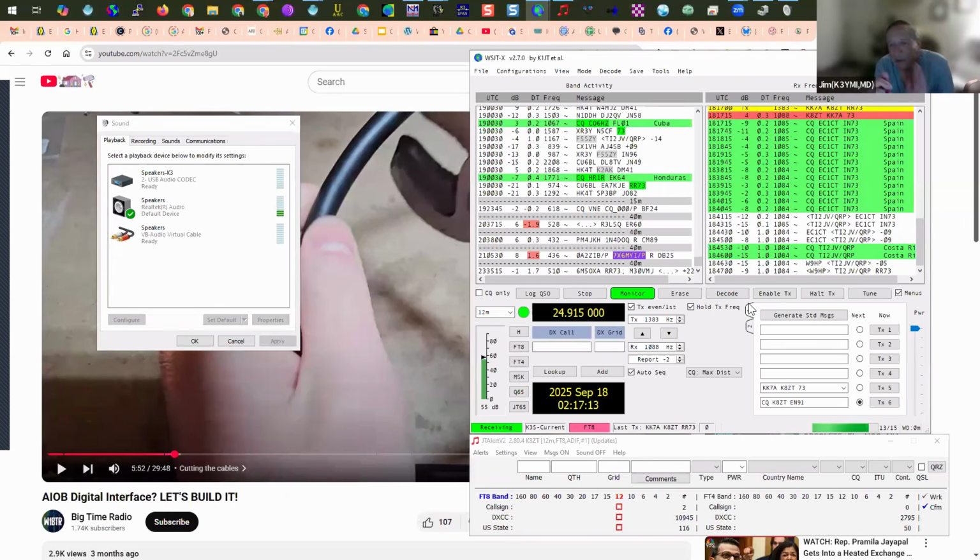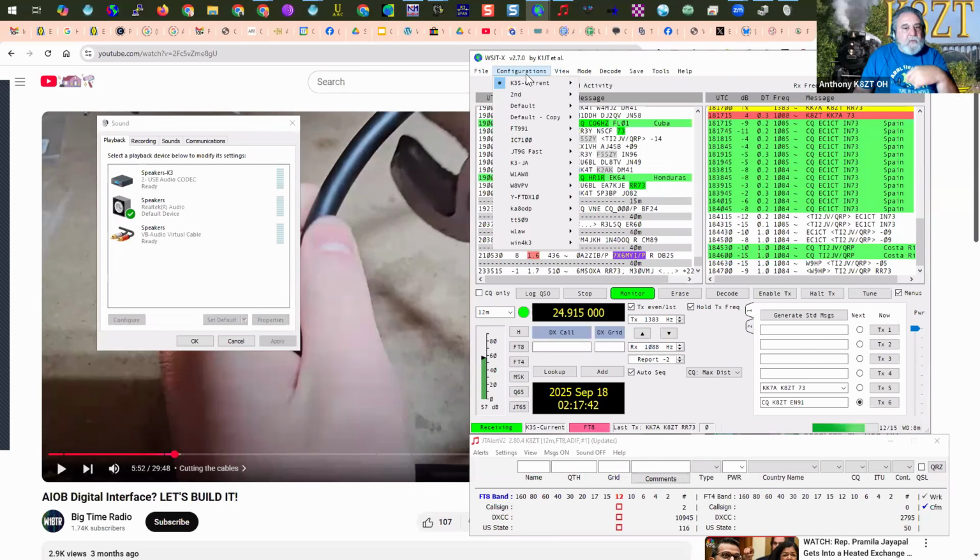Right, so let me be clear. I'm not going to run the 7300 and the Yaesu radio simultaneously. Okay. I'm just going to now run the Yaesu radio, and the DigiRig will be configured appropriately. But I'm wondering, do I need to use a different one, well, maybe I won't use a different one. Let me see if this answers your question, because this is what I'm guessing might be part of your question. If you look at WSJT-X here on my screen, you'll notice that there's something called configurations. Correct. So you want to set up a different configuration for each radio that you're using.